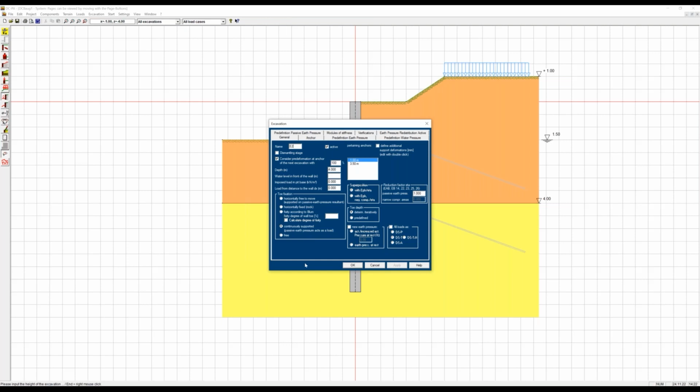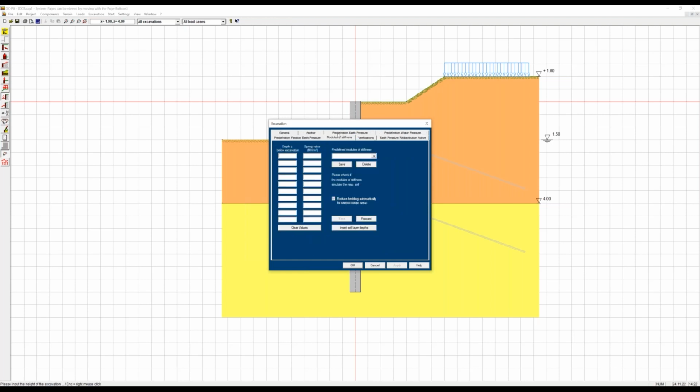Instead of applying a ground support with passive earth pressure, we might define moduli of stiffness. This is for elastic bedding. Here we may as well predefine values, and these values give an elastic support with many small springs, leading to some deformation when there is load on the springs.